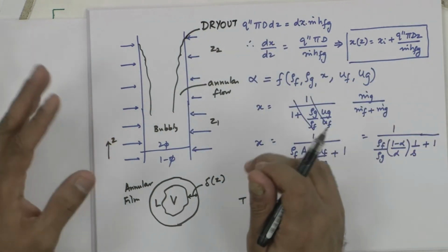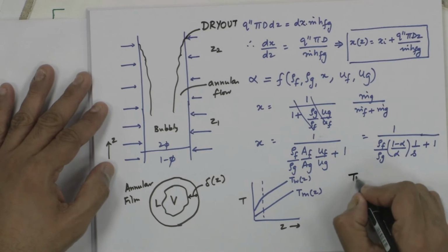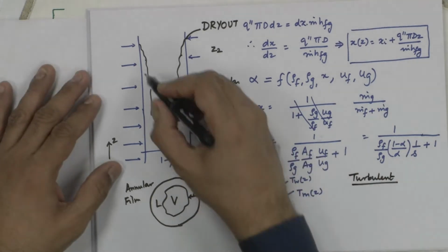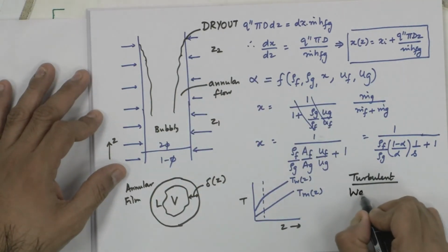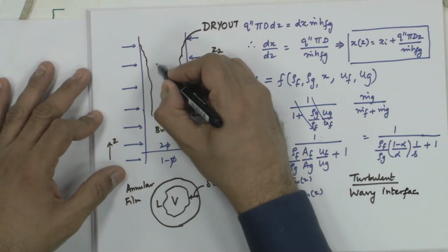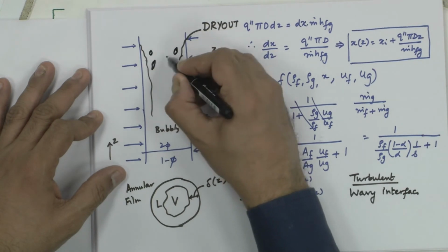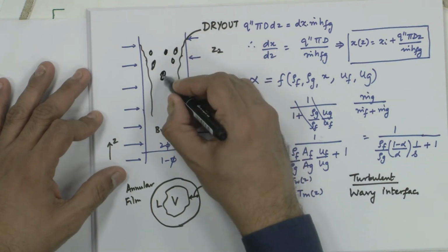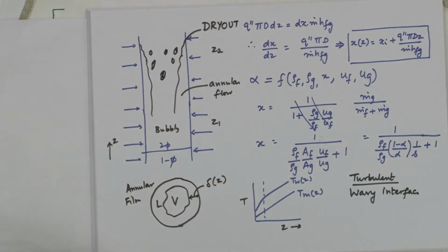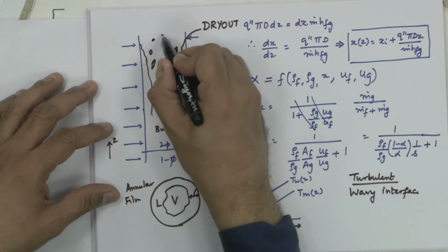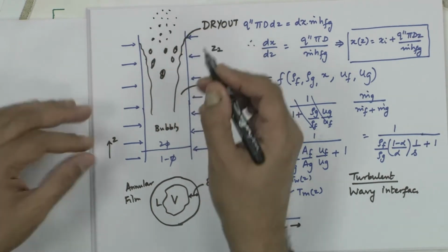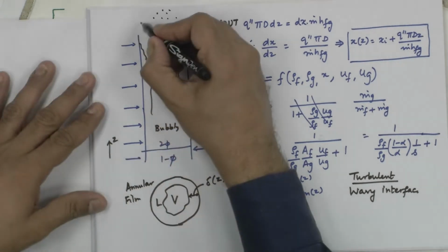But remember, the flow is extremely chaotic, turbulent. Most of the two phase flow situations would be turbulent, random. So, the liquid and the vapor film interface will be very wavy, nothing will be smooth here. There will be liquid which is sheared as droplets, ligaments, etc. So, there will be large liquid droplets and those would get sheared because of the difference in the velocities of the liquid and the vapor, and what you would see eventually is small droplets, and finally if I go ahead I would get to see very small droplets, and finally no more droplets present.